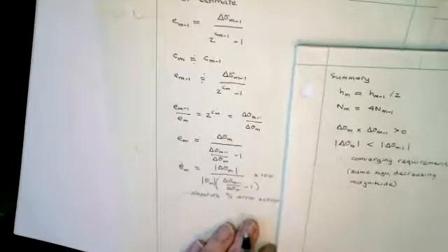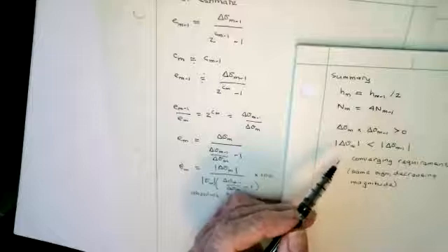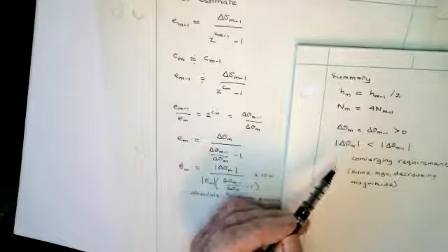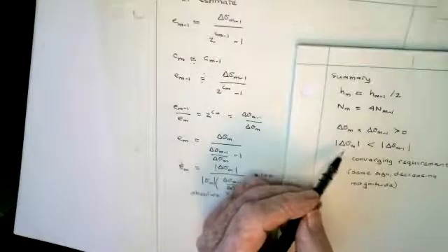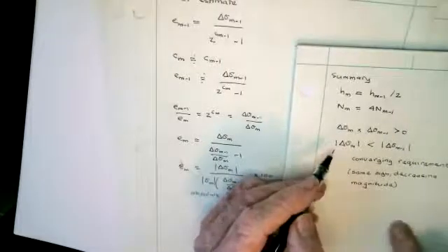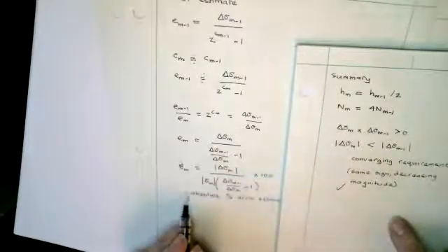It's going to turn out when you do some finite element, occasionally these things change sign. When that happens, it's called non-monotonic convergence, and it's very difficult to estimate the errors reliably. What's also going to happen is if you have a big enough stress concentration, the stress increments initially will be increasing as it tries to get up to this big stress. And then when you get closer, it will start to decrease. So we're going to wait until it starts to decrease before we estimate the error. Only when this holds do we estimate the error with this formula.